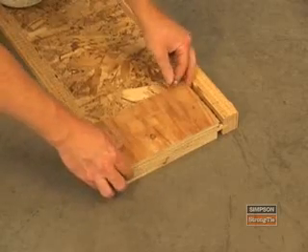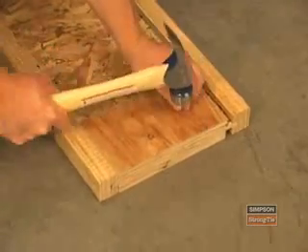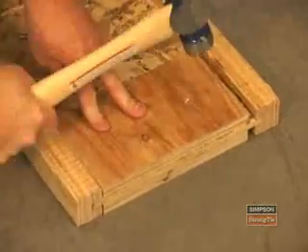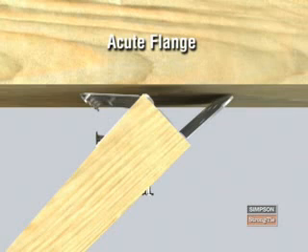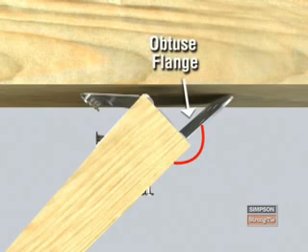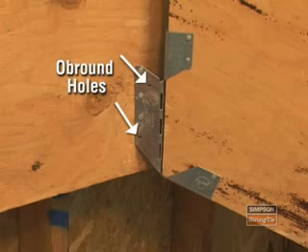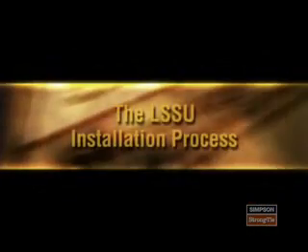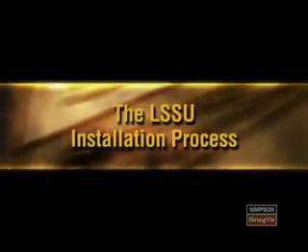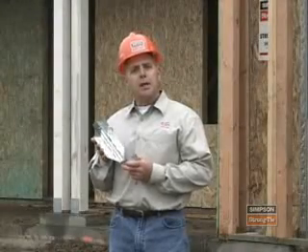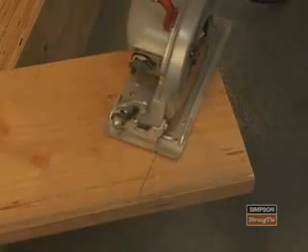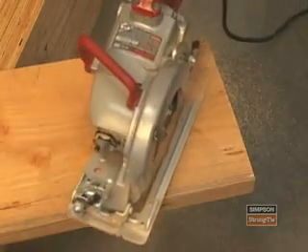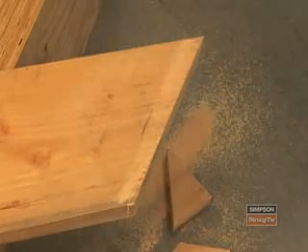When using an LSSU with I-joists, remember to first add web stiffeners to the I-joists as required by the manufacturer. An LSSU series hanger has an acute flange and an obtuse flange when skewed. It also has seat nails and ob-round holes. For skewed applications, there's no need to cut a skewed angle. For sloped rafters, however, you must first cut the joists to the desired slope.